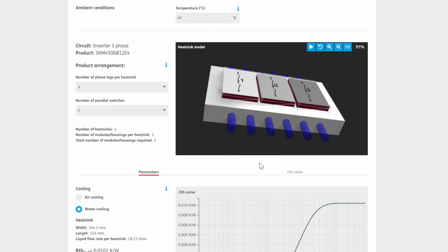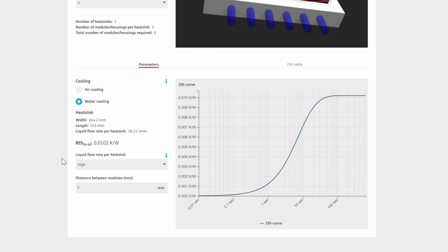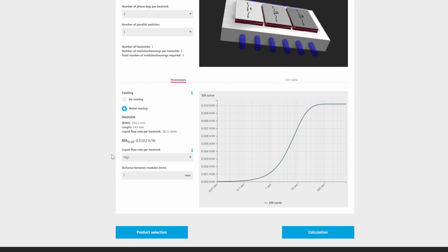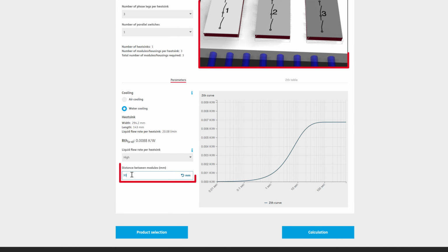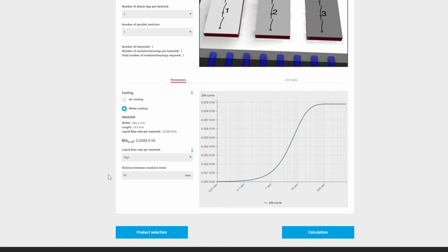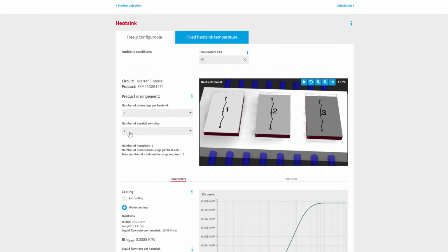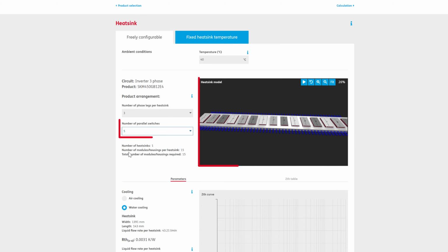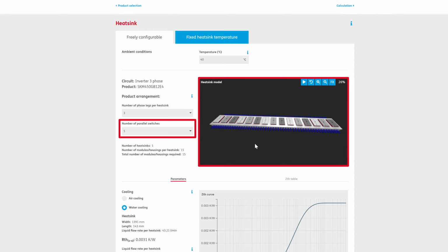The distance between the modules influences the thermal coupling factor. However, at more than 25 to 30 millimeters, the heat sources are thermally decoupled. A wider distance does not improve the cooling any further. Because each power module is more or less considered thermally independent, no limitations exist in the mechanical dimensions for the simulation model.